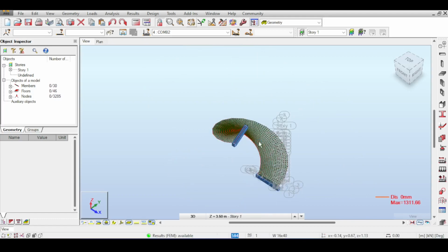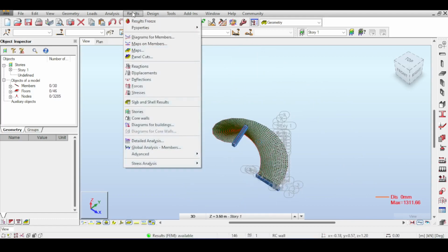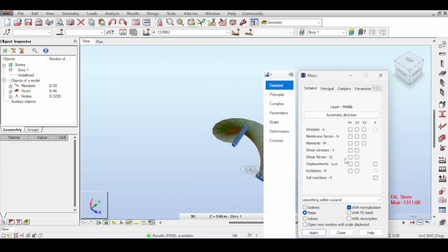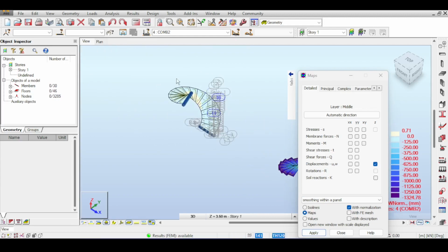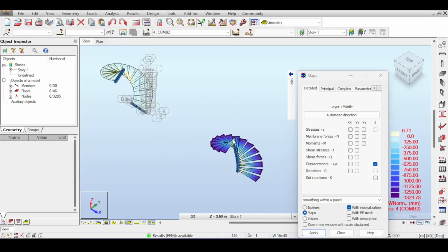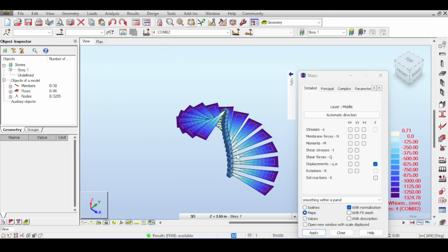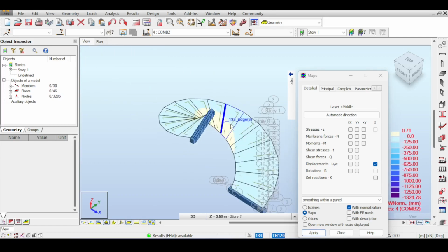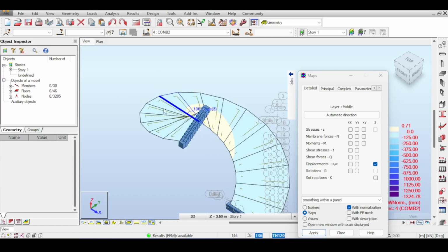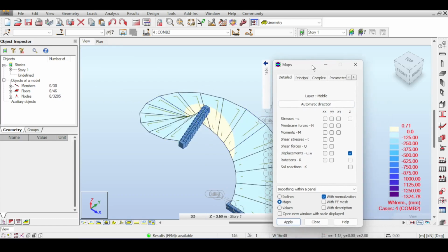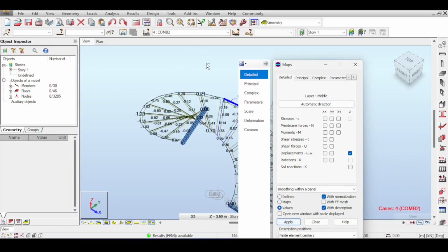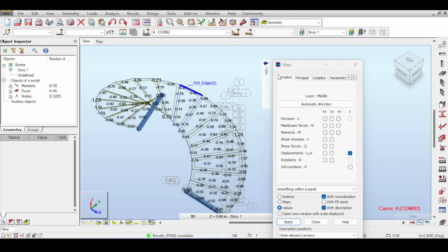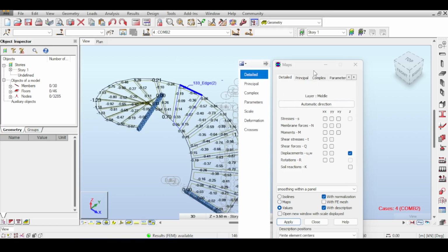Let's take a look at the concrete deflection. So I'll go to results and go to maps and ask it to open the Z map here. Of course, now the problem is that this affects the scales here. Because this is so huge, you see very small scales here, but in actuality, it's not small. So I'll open the values now and click on OK or apply, hoping that it fixes something. Yeah, now I see values, which makes a little bit more sense.